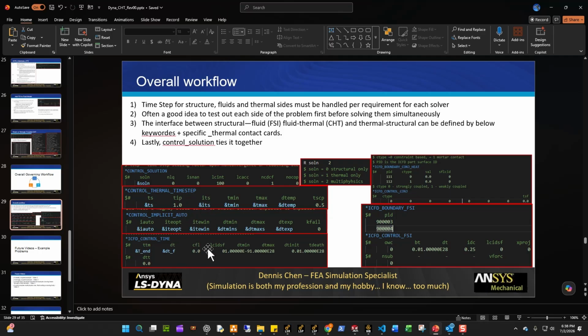Then you have to make sure they couple together correctly, right? You have to consider how they're going to couple together in terms of the DT. The DT is very, very different. Is that really adequate? Maybe you have to reduce the DT even further to account for a strongly coupled fluid structure interaction problem, in which you have to set your structure DT to the same as your fluid DT. But your fluid DT is going to be way smaller, which is what makes the FSI problem very expensive to solve. Okay?